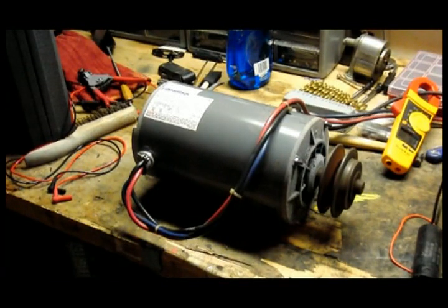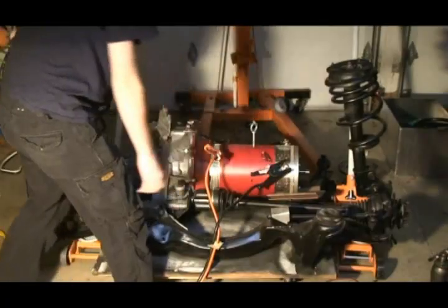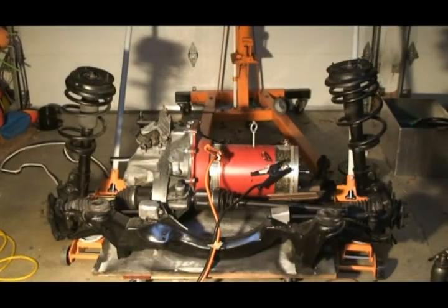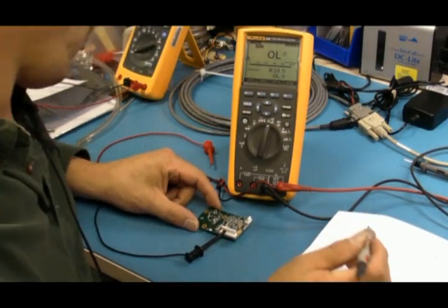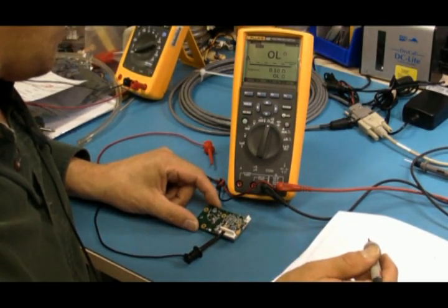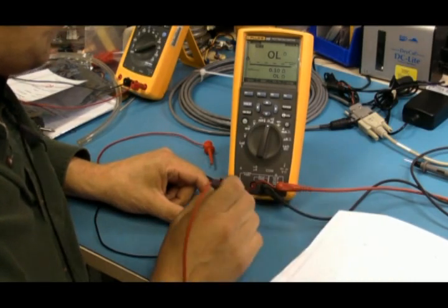Motor test equipment can be either offline, with no power supplied to the motor, or online, where power is applied and the motor is running. Motors can be tested either standalone on a test bench or in situ, where installed in the equipment they power. The test equipment itself uses internal voltmeters, ammeters, and ohm meters to measure and calculate a motor's various performance parameters.